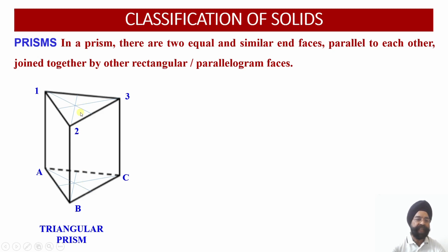I can name this as O or O1 as it suits you. One end point of the axis I will name as O1, and the second point of the axis I will name as O. So these are construction lines which I have to draw in order to obtain the center point or the axis point of a triangular lamina. This is how you locate the axis of a triangular pyramid or a triangular prism.